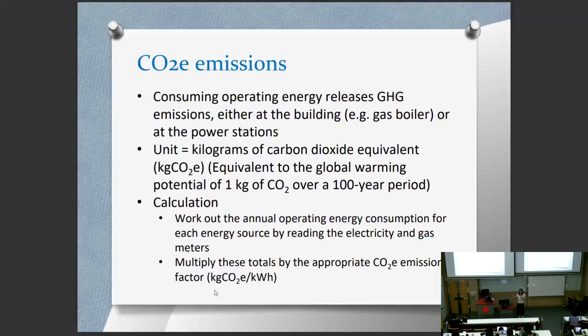Maybe 0.4 something kg carbon dioxide equivalent per kilowatt hour. Then I can multiply this emission factor by the total electricity consumption at my home, and I will be able to find out the operating carbon due to electricity consumption.